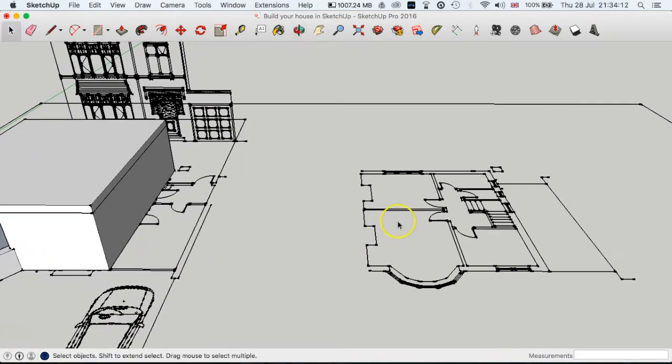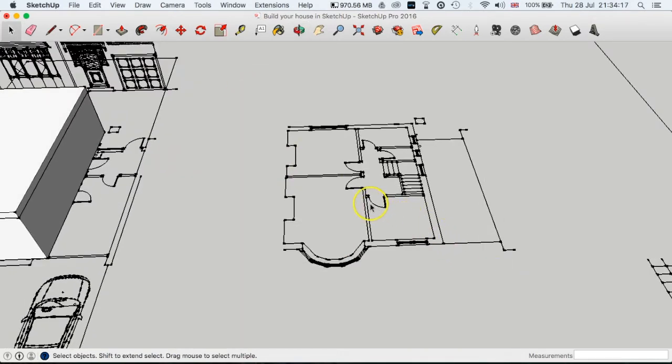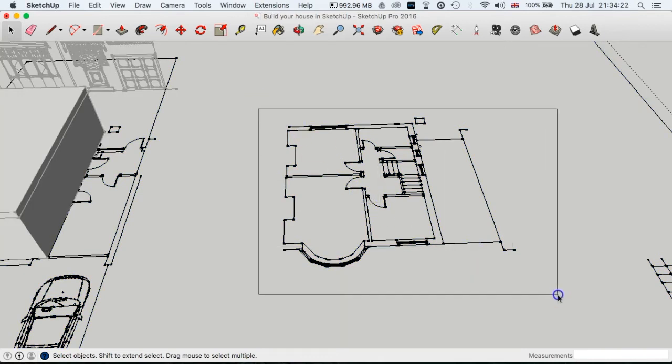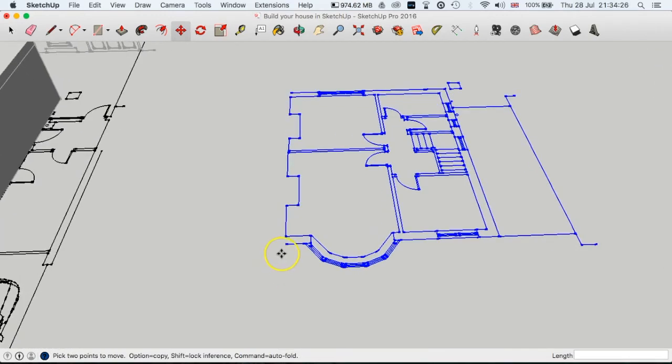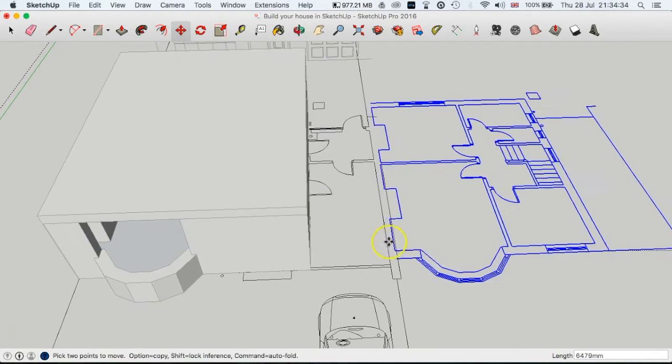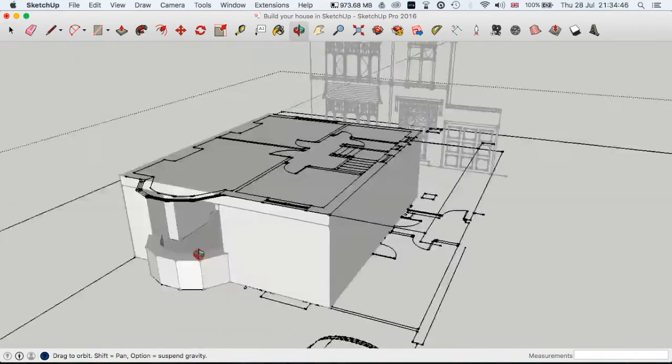Now what you need to do to create that second part is, using the first floor one you can see here, double click, select it, press the M, and we'll use this one here. What we're going to do is move it to the point we know. Place that there, select out of it, and then what you've got is the makings of your first floor.